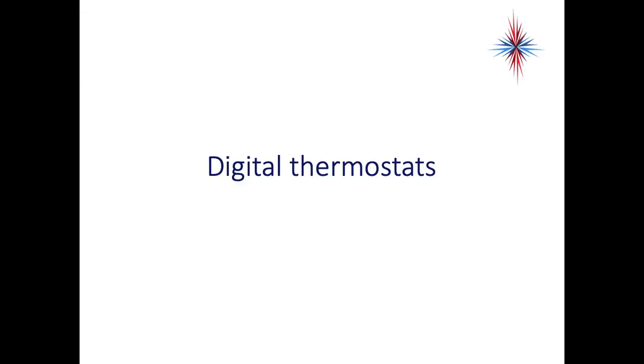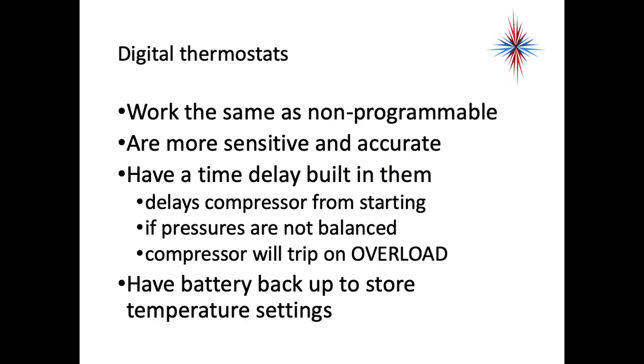So let's talk a little bit about digital thermostats. They work the same as non-programmable, but they're more sensitive, and most of the time they're more accurate. They have a time delay built right into them, which delays the compressor from starting if pressures are not balanced. And it sometimes prevents the compressor from tripping on an overload situation.